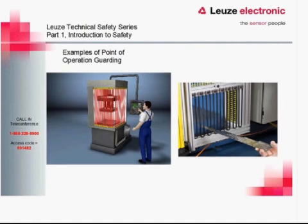So the first would be an example of a point of operation guard. Here we have a small process machine, a little press, light curtains, small resolution on the light curtains, fingertip control. That way anybody gets into this, the machine stops, press stops cycling. A hard guard version of something similar to that would be this. Very small openings, can't get your fingers in far enough to get to the dangerous point.